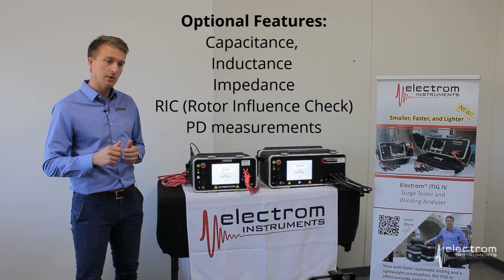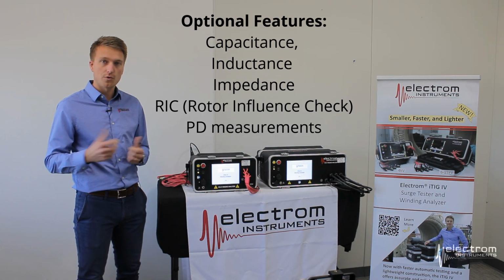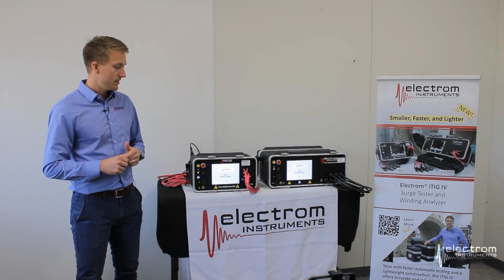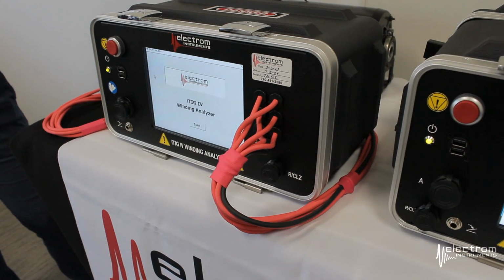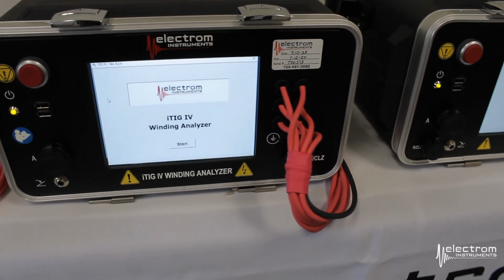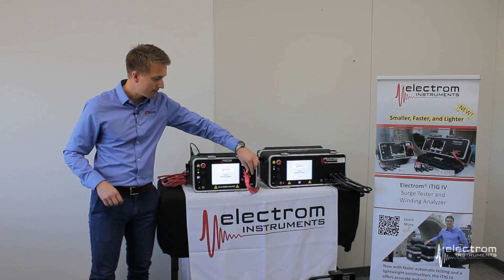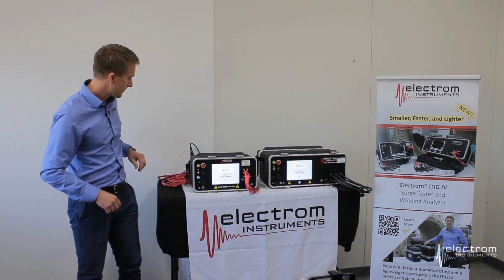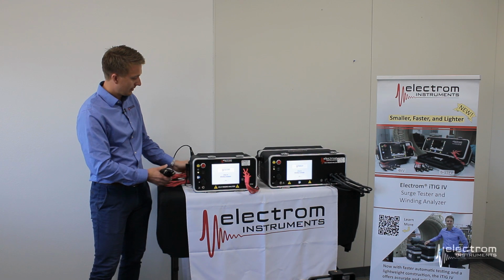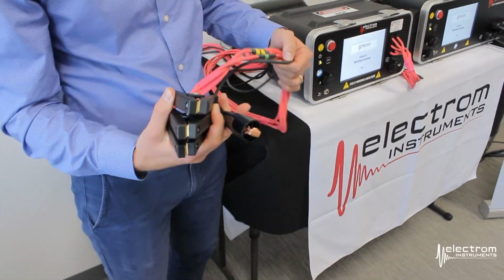Optional features include capacitance, inductance, and impedance, as well as RIC, rotor influence check, and partial discharge measurements. The Model D has one high voltage lead set that does all the low voltage and high voltage measurements and tests. There is one black ground lead, and there are 6 red high voltage leads. The 6 red high voltage leads are terminated in 3 clamps labeled 1, 2, and 3 to correspond with phase 1, 2, and 3.